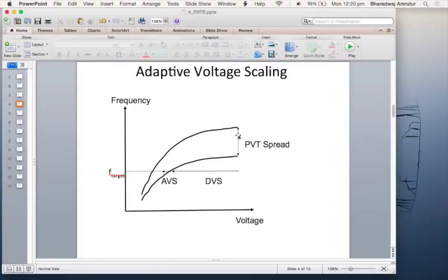Also, of course, the energy comes down, because dynamic energy consumption is half alpha CV square. So as I reduce voltage, energy comes down, which is, energy per operation also comes down. So this is very important for battery operated systems. Say I was not connected to the power here and it is running off the internal battery, then I can prolong the lifetime of the battery.